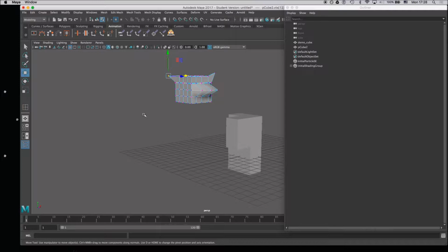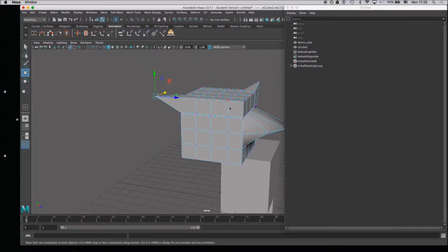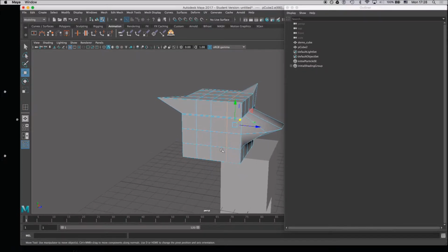Right. So when you have an edge loop, pretty much every edge loop can be selected by going to edge mode. I'm selecting the edge loop by double clicking it, and that selects the whole ring. Sometimes that doesn't work, so you might have to actually go in and select everything, but it's a pretty simple primitive, so I can do that. And then once you select the edge loop, you can hit W to go into the Move tool, and you can shift that around. I definitely don't want to move it all the way over here. It's causing some problems, but yeah.